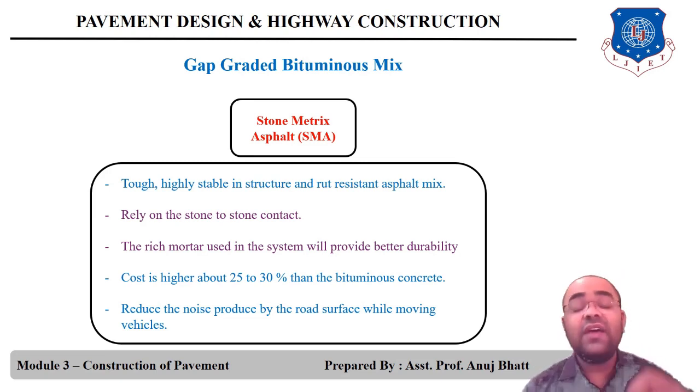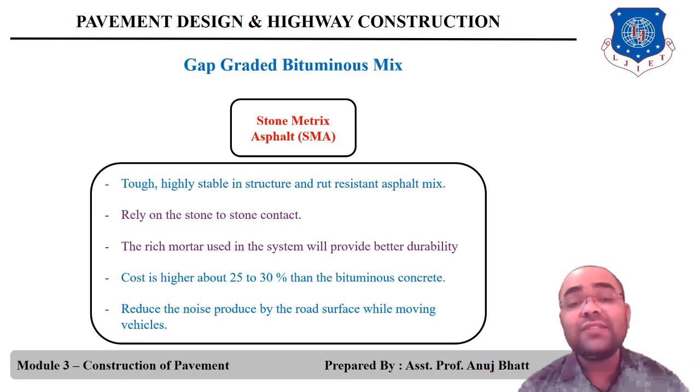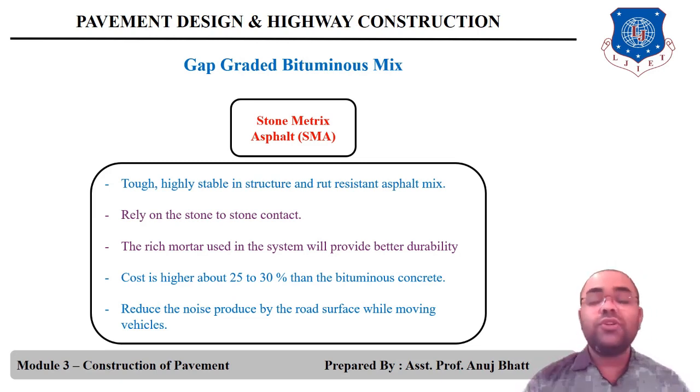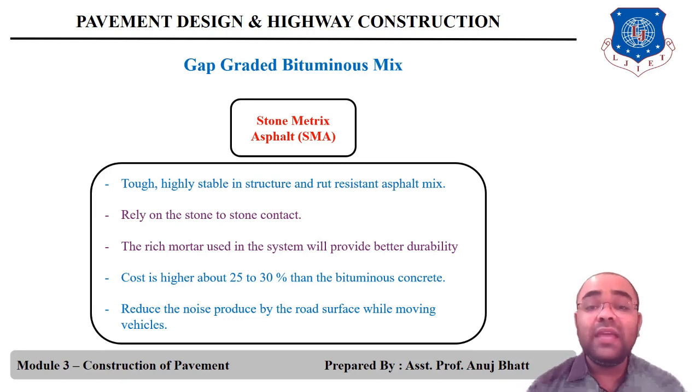So if there are more vehicles on the road and more stress on the road pavement, this particular mix will give strength to the surface as it relies on stone to stone contact. In this mix, a rich mortar has to be used, which will provide better durability.